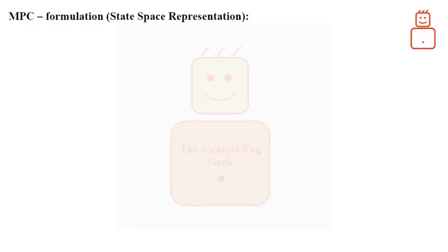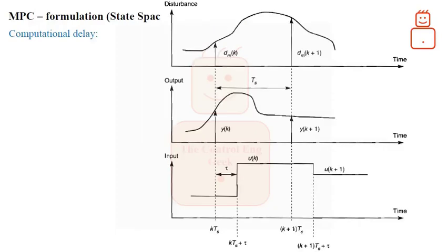Before jumping into the last portion of the MPC problem, which is the prediction based on the given plant model, I would like to introduce the effect of computation time delay on the MPC problem. As the MPC controller is an online controller, the MPC problem requires some time to be solved in between the samplings, therefore, this time delay should be accounted for in the MPC problem. The following figure illustrates how this computation delay is handled.